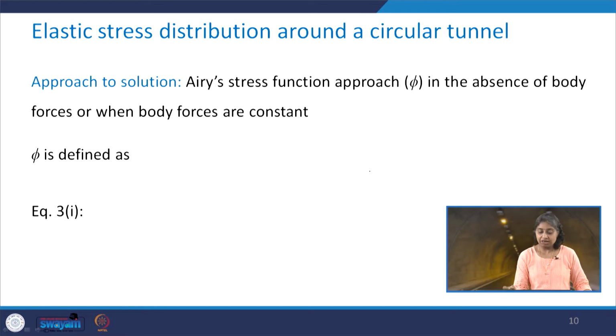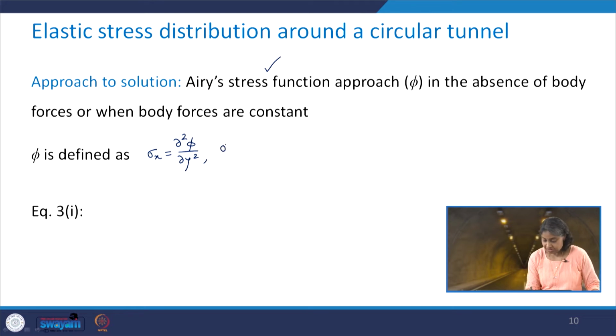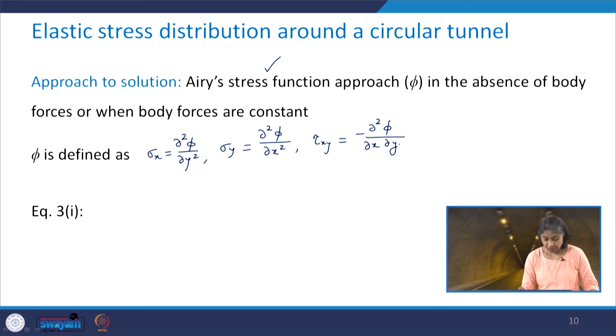We have Airy's stress function, denoted by phi, and if there is an absence of body forces or the body forces are constant, then phi can be defined as sigma x equal to del 2 phi del y2, sigma y is del 2 phi del x2, and tau xy is equal to minus del 2 phi del x del y.